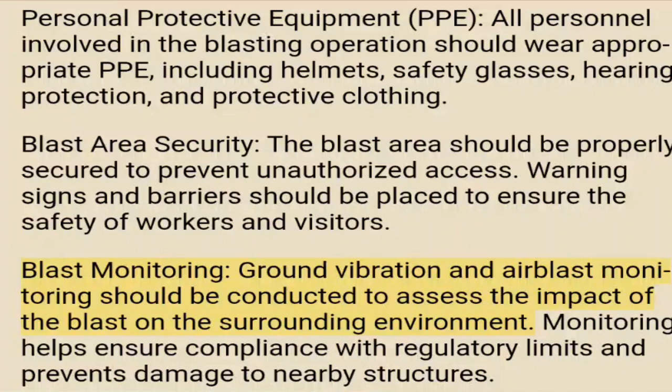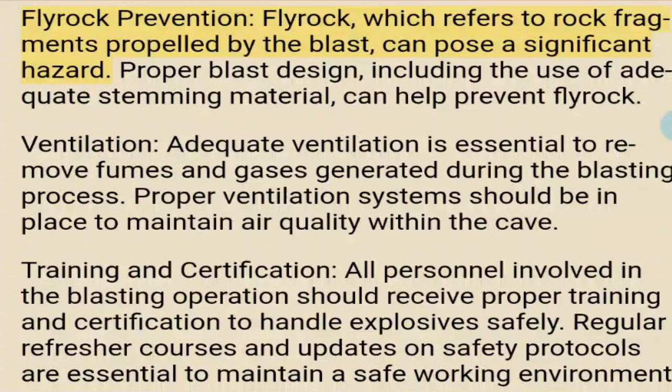Blast monitoring. Ground vibration and air blast monitoring should be conducted to assess the impact of the blast on the surrounding environment. Monitoring helps ensure compliance with regulatory limits and prevents damage to nearby structures. Fly rock prevention. Fly rock, which refers to rock fragments propelled by the blast, can pose a significant hazard. Proper blast design, including the use of adequate stemming material, can help prevent fly rock. Ventilation. Adequate ventilation is essential to remove fumes and gases generated during the blasting process. Proper ventilation systems should be in place to maintain air quality within the cave. Training and certification. All personnel involved in the blasting operation should receive proper training and certification to handle explosives safely.